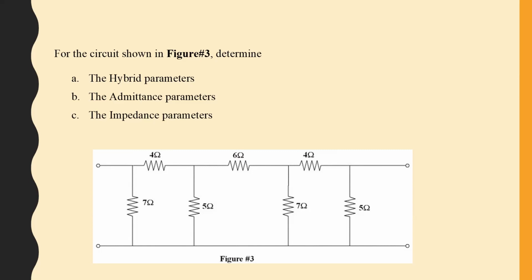My analysis, I can see 2 pi networks that are symmetrical. Are they symmetrical? They are not. Remember, symmetry means that it's the same network from either port. So if you take the 2 pi's, they are not symmetrical, but you do have 2 pi's.